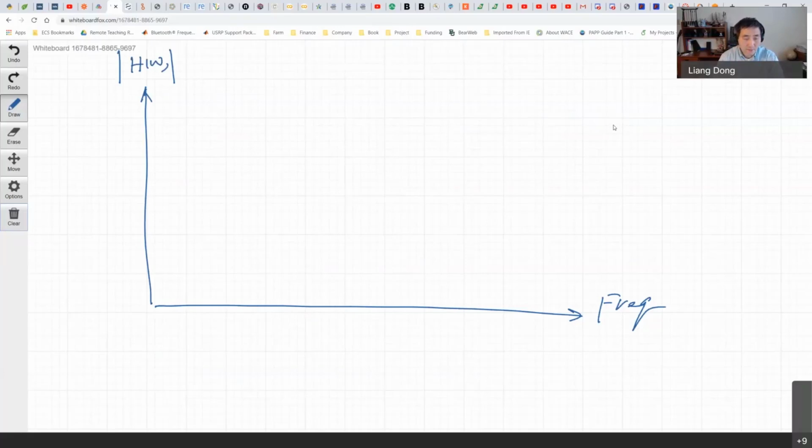Look at a simple one, a low-pass filter. So for the low-pass filter, I have a cutoff frequency, omega c here. What I want to have in an ideal case is like this. Cutoff frequency, and then it's 0. So I want to have a 1 here, 0 here. Low-pass filter, right? From 0 to omega c, we pass the signal. From omega c, the cutoff frequency, to pi, that's the highest frequency, I want to have all zeros. That's a low-pass filter. We're looking at the amplitude of my frequency response, h omega.